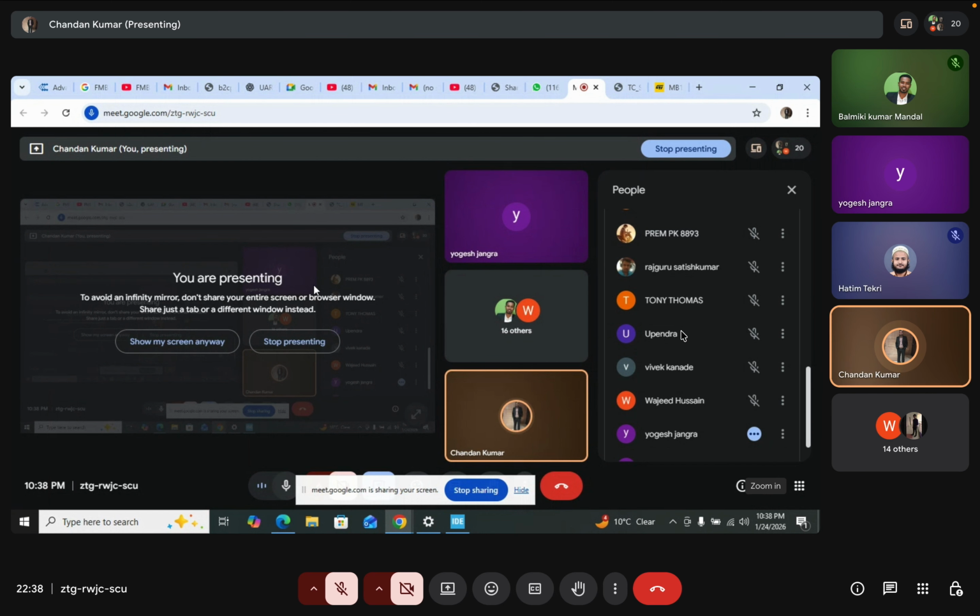If your first pin is PA1 and the first option shows PA2 for the other pin, then you should stick with your options. If you are using option 1, you should use PA1, PA2. If you stick with option 2, you should use PB2 and PB3. In rare cases you can use the RX pin of the first option and the TX pin of the second option, but this needs modification in your PCB. With some minor modification, you can use it also.